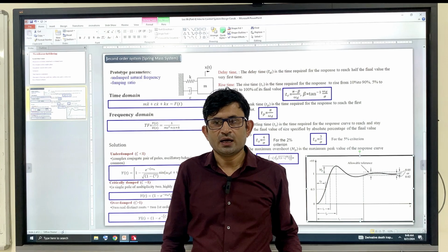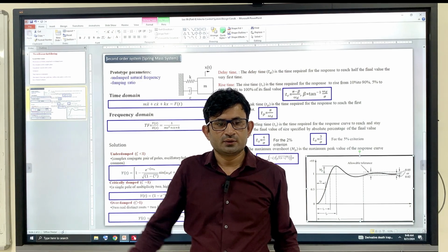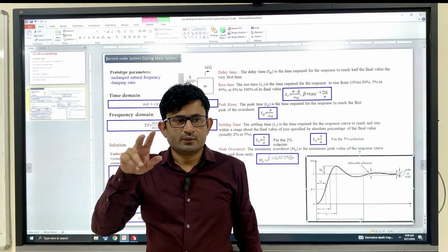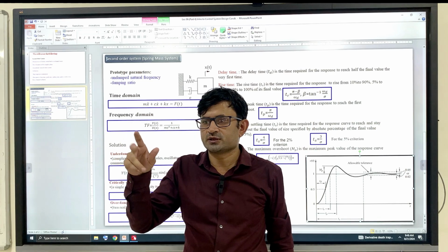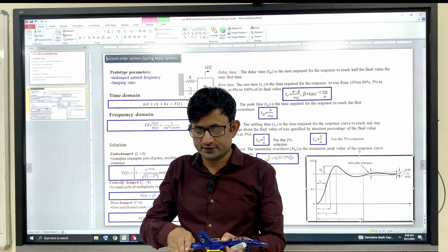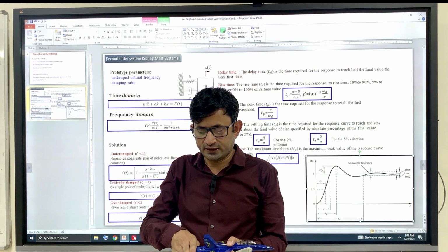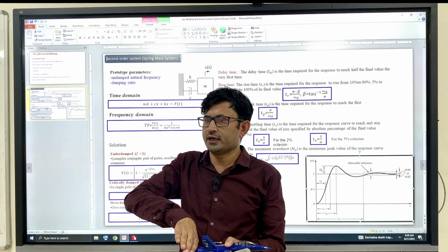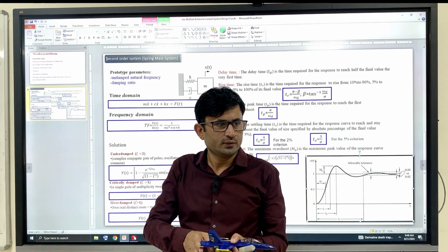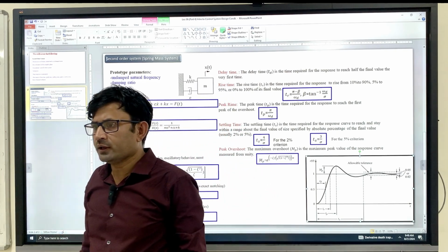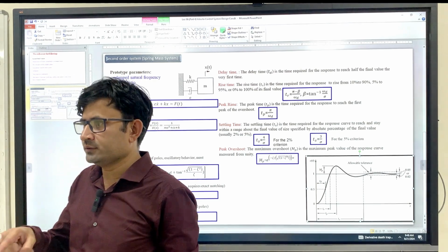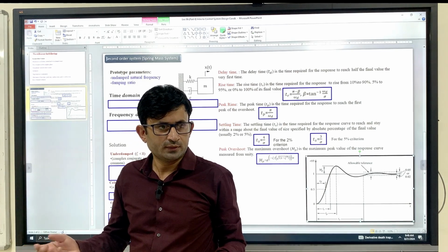For example, we generally do not command a 70-degree bank suddenly, right? We generally put the saturation at plus minus 30, plus minus 50, right? And for example, let's say the elevator, we can deflect 10 degrees up, 15 degrees down, okay? Beyond that we cannot deflect, right? See, we cannot rotate 360 degrees, right? It's meaningless, right?